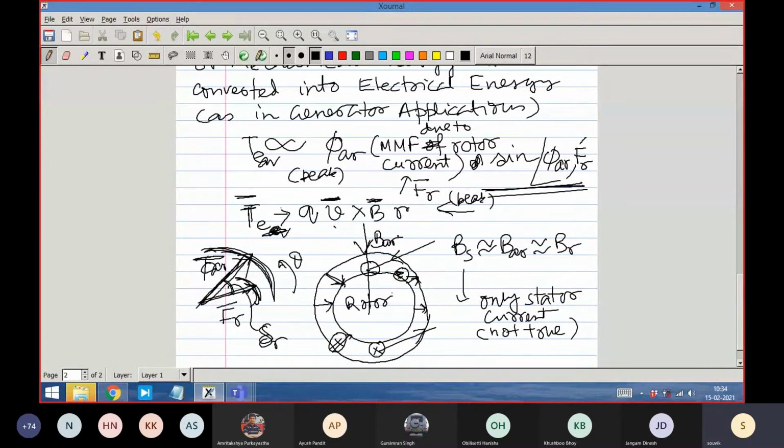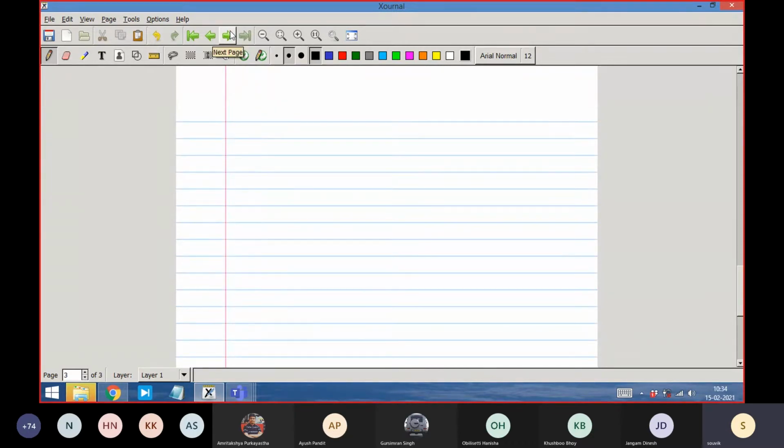So, if that is clear, let us take this a little more conceptually in another picture. Let us take a machine. What are we trying to do then? As I said, I will be creating flux in the air gap, and creating rotor MMF. So they are, in other words, nothing but creating two pole pairs, one for stator and one for rotor. Magnets. We are creating as if two magnets. That is the essential interest, and these magnets would like to align, and the intention to align will be termed as torque, the production of torque.